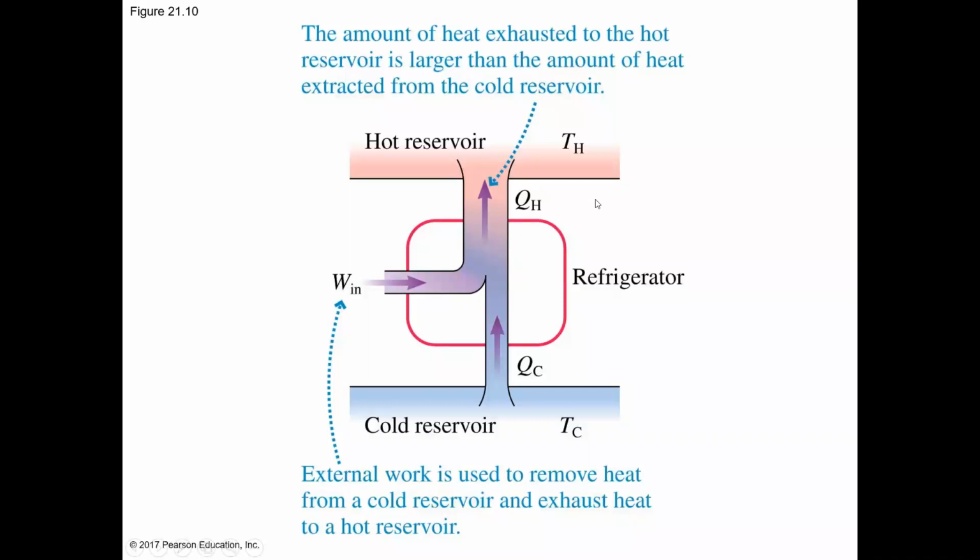So again, it seems a little counterintuitive. It seems like you're getting something for nothing, but you're not. You're not creating energy. You're just assisting its flow. So let's just stick with the numbers I've been using, 200, 1,000, since the coefficient of performance is 5. You pay for 200 joules of energy from the power company, and that induces the working substance of your heat pump to transfer an additional 800 joules of energy from the air outside your home into the air inside your home.